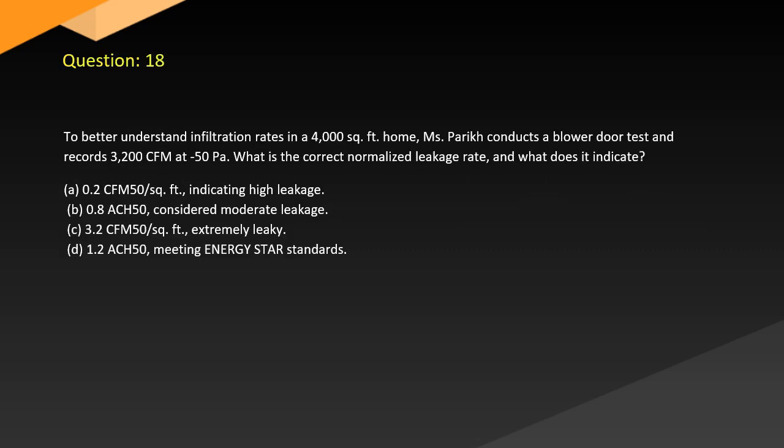Question 18. To better understand infiltration rates in a 4000 sq ft home, Mr. Parrot conducts a blower door test and records 3200 CFM at -50 Pa. What is the correct normalized leakage rate and what does it indicate?